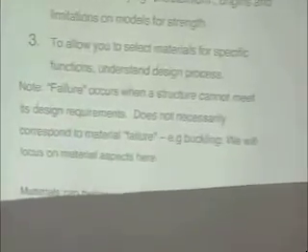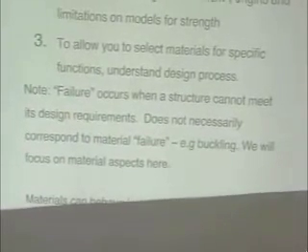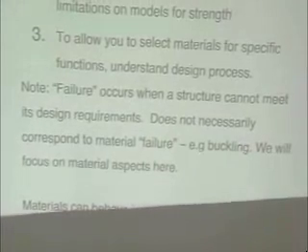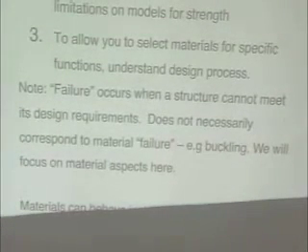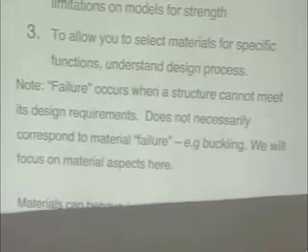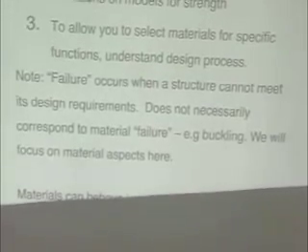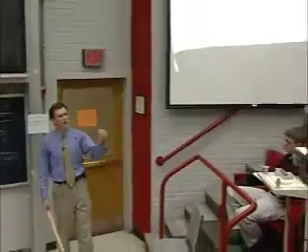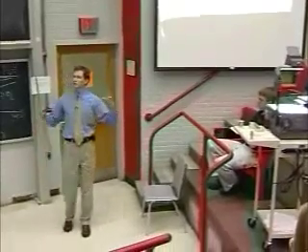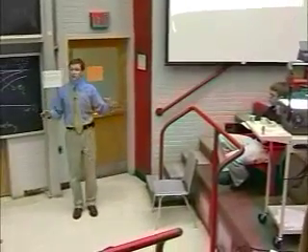But before we get, sorry, one final thing. Just be a little bit careful, and this ties back to part of the quiz, that we need to distinguish between the material response and the structural response. If we're designing an airplane or a launch vehicle, satellite, whatever, we're ultimately interested in structural performance. We're interested not so much in the material failing or the material being stiff enough, but in the structure failing or the structure being stiff enough.